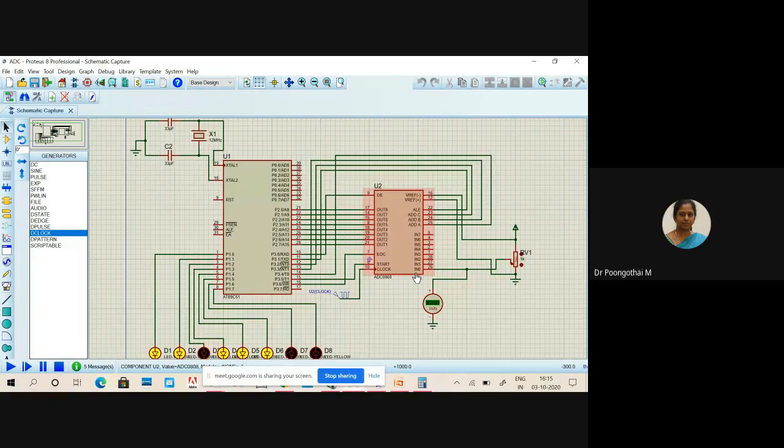Okay. So once the channel is selected, we have to latch the address. So that is done by ALE. So which is ALE here? Where is ALE? So here. So we have to latch the address. So that is done by P3.1. So the address is provided by these 3 pins. That is your 3.4, 3.3 and 3.2. So once we have latched, next we have to start the conversion process using this SOC signal, start conversion signal.